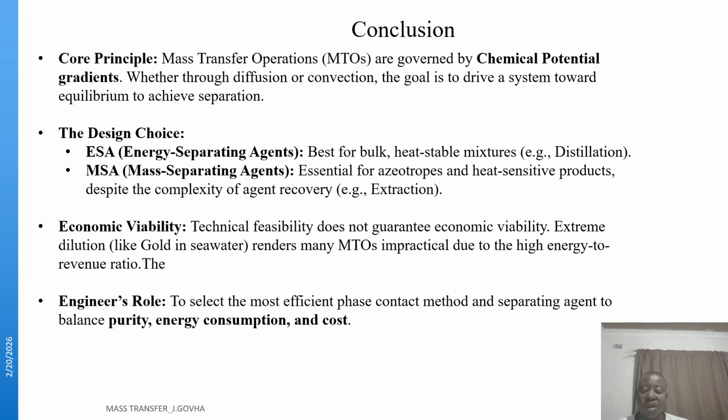One extreme one is extreme dilution, which renders many mass transfer operations impractical due to high energy to revenue ratio. So you as an engineer, what's your role? It is to select the most efficient phase contact method and separating agents to balance the purity, energy consumption, and your costs.